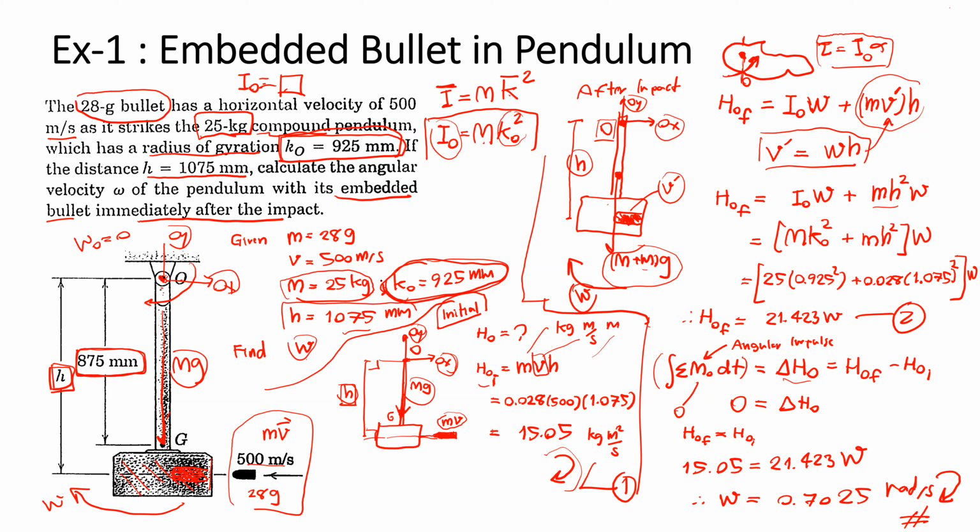When you work in the future, if you need to deal with this type of problem and you get the information from the data sheet or the catalog of the mechanical part, please remember that they may give you the mass and the moment of inertia about the x-axis, y-axis, z-axis, or they may give you the radius of gyration about that axis.